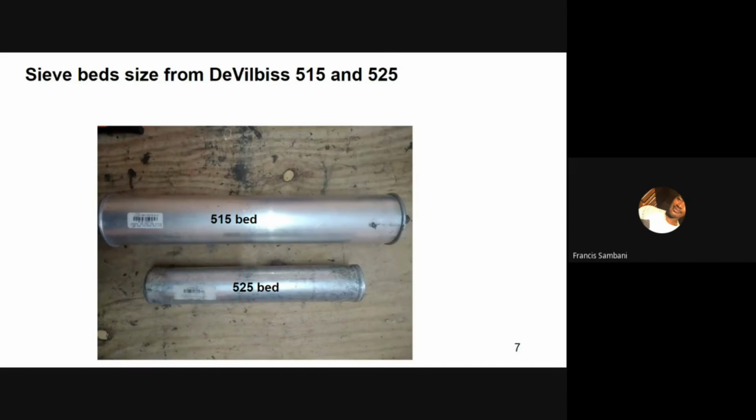One thing we can also look at is the timing and cycling of these concentrators, for example between the 5 liter and the 10 liter equipment. This timing has nothing to do with the compressor, and more to do with the volume and size of the sieve beds and absorption pressure. So using the same model of compressor, it will take longer to reach 30 psi with a larger volume sieve bed than with a smaller volume sieve bed.